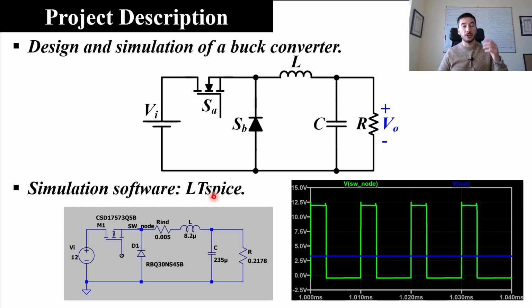So in this way, if you want to choose or evaluate what happens if you use a particular MOSFET like this one, you can download the simulation model of the manufacturer, put that model in your simulation circuit, and check the results you obtain. So in this way you can obtain, let's say, results that are similar to the ones that you obtain in a real prototype.